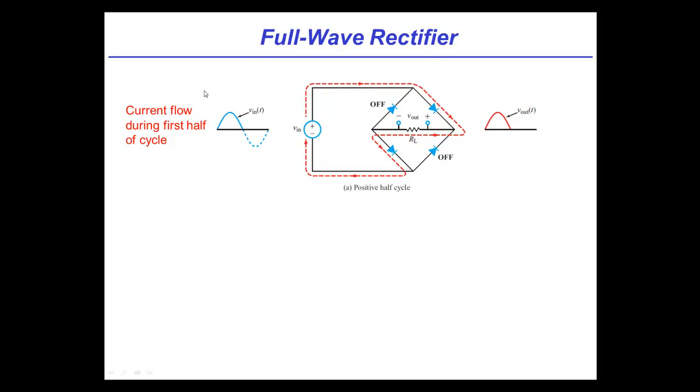That's right, and the solution was the full wave rectifier. So remember, the key point of the full wave rectifier is voltage is relative. Okay. And if voltage is relative, all we need to do is make sure that we route the voltage around such that we always have a positive going to one side of our DC circuit requirement and a negative going to the other. And I'm going to explain to you what that means.